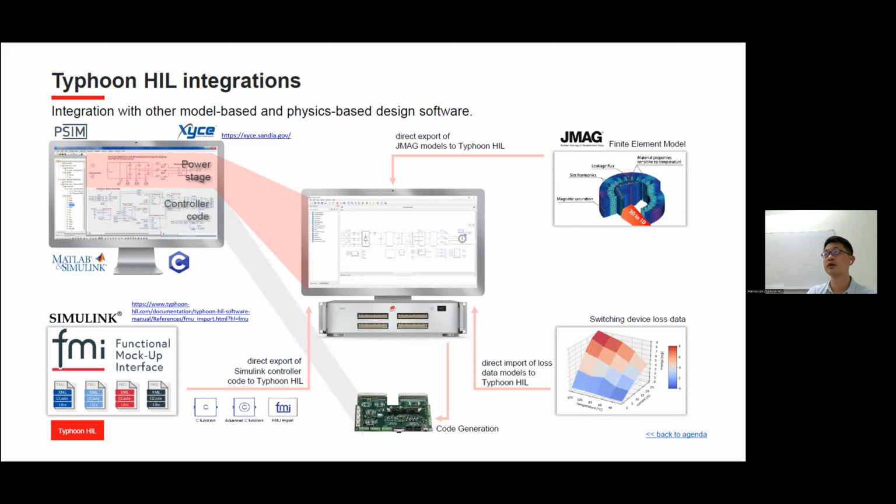The other one, let's say you're using PSIM, is even more seamless because PSIM and Typhoon HIL had a joint project to integrate each other's environment. In PSIM, you have a button that will export everything into Typhoon HIL, and in the Typhoon HIL environment, you can import the file directly from PSIM. I will send you more details on how you can do this integration from Simulink to Typhoon HIL. This is the functional mockup unit, and we are still improving as the days pass.